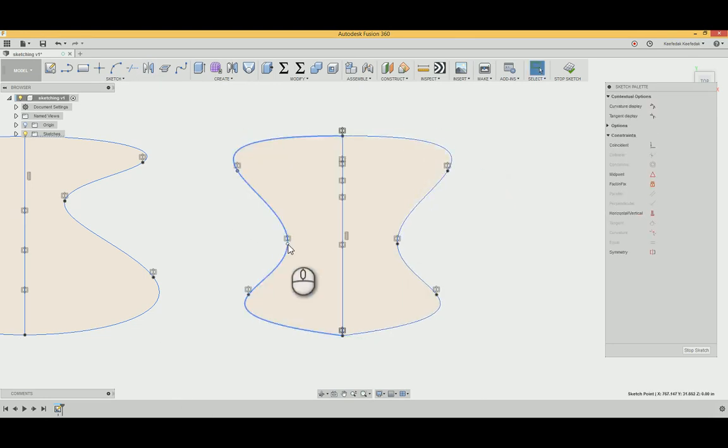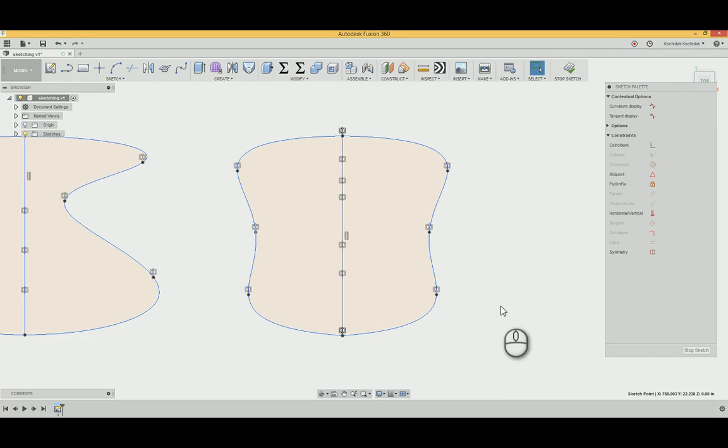So, quick question about the points. I missed something in the middle there. You're putting 2 points on either side of the line, and then you're making those symmetrical to each other. Basically, they're symmetrical to the line in the middle. Okay, so the constraint is you click on one point and then the line. No, you click on the two. You click on one thing, the thing you want it to be symmetrical, and then the mirror line.